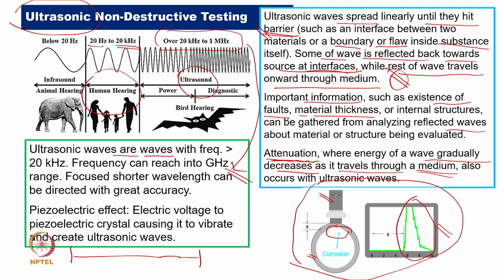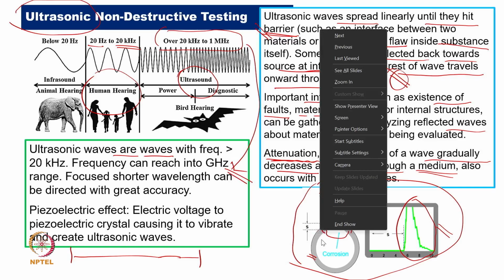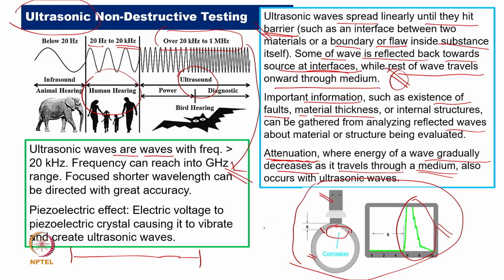If the wave goes from top to bottom of a surface, it will have some attenuation, and that needs to be recalibrated. Also, this calibration will have some range, maybe valid only from 1 to 3 mm. If you use less than 1 mm, it will not be useful. If it is less than or more than 3 mm, it will not be useful.